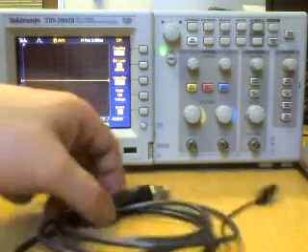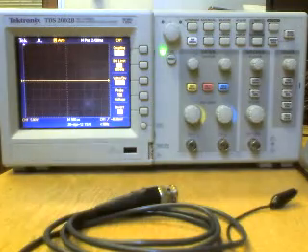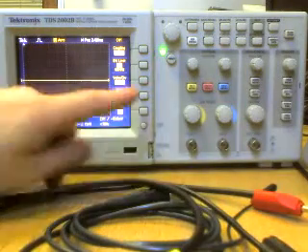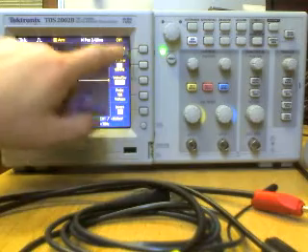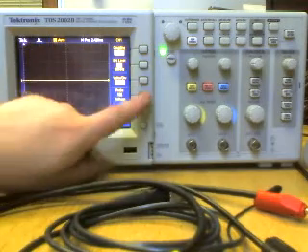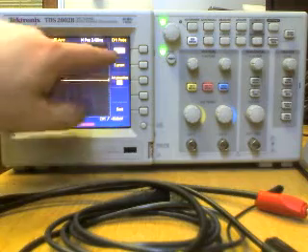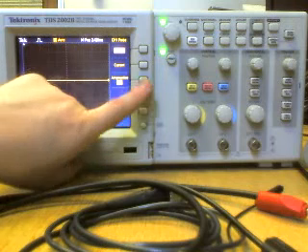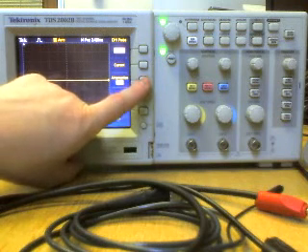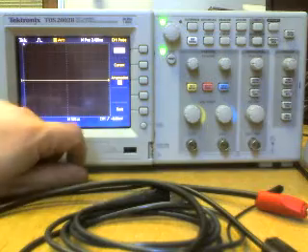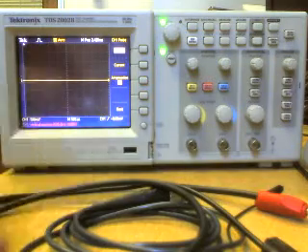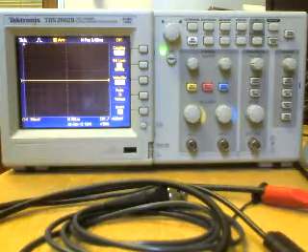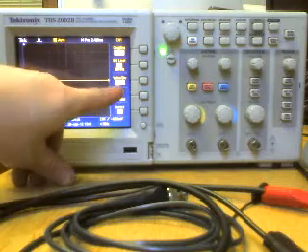Okay. If it was a trusty BNC cable, this thing here, without any attenuation, you would have to go into this menu. So all this menu is driven by the buttons next to the menu. So you go into the menu and you say, I want a voltage probe of 20, nope. 50, no. 100, no. 500, no. 1000, no. 1, ×1. So if you were using a BNC cable like this one, you change this to ×1 and go back, and we have a probe value of ×1.